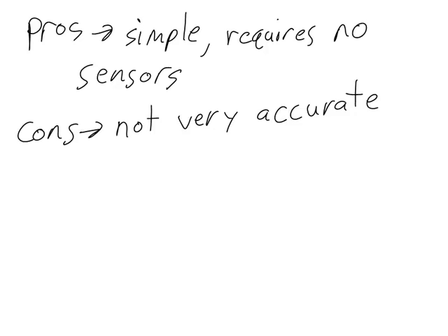The motor velocity constant is affected by things like the load at the end of the end effector and friction internally to the motor. And so we'll find that when we use open loop position control, the end effector does not always end up getting to the position we were intending it to get to.